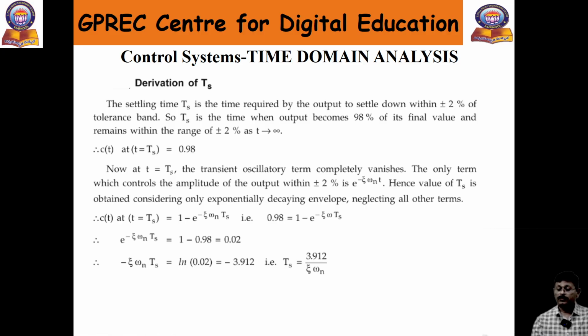So generally for settling time you are taking plus or minus 2 percent of the overall value. So the 100% you are taking plus or minus 2. Okay. So I am taking 1 or 0.1, what is 1 minus 0.02? 0.98. Right? So there I am taking the 2%. When you take the 2%, substitute in the main equation, the value equal to 0.02. Apply the log, because of the exponential, apply the value. So minus ln 0.02 is approximately 4. So t is equal to 4 by zeta omega n.